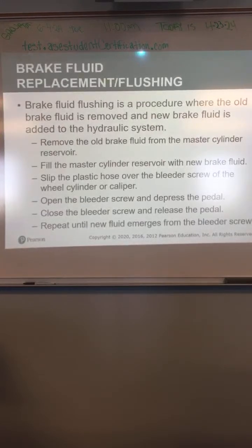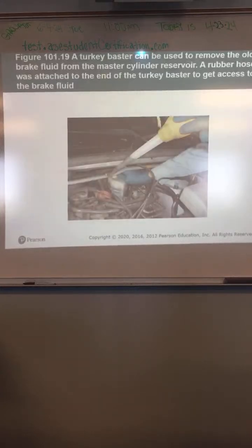Replacement or flushing of the brake fluid. All that is removing the old brake fluid, installing new brake fluid, right? Remove the old brake fluid from the master cylinder, fill it with new fluid. Slip the plastic over the bleeder screws, open them up, depress the pedal, let it push the old fluid out. Repeat it until you get new fluid out of the bleeder screws.